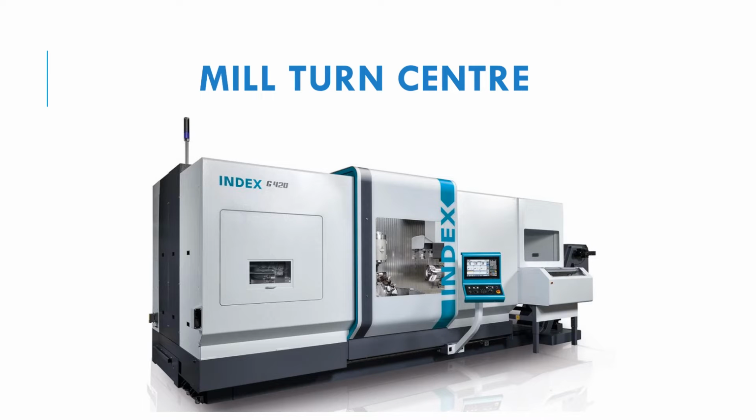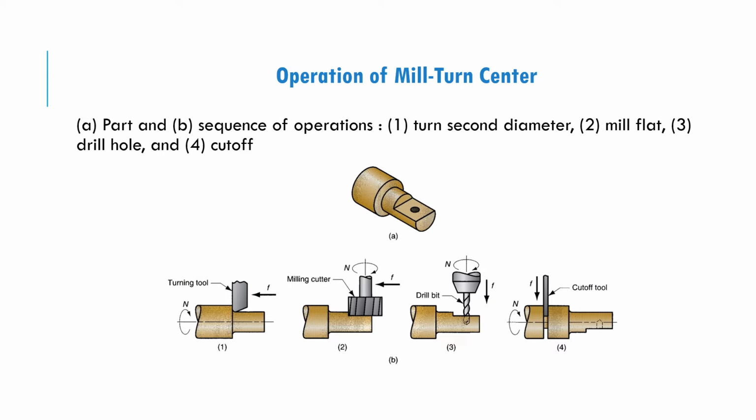This is an example of the latest mill-turn center available in the industry. This is an example of the operation of a mill-turn center. For example, part A is produced via the mill-turn center. What is the sequence of operations during this process? For the first one, the turning process takes place, where facing and shaping get the right dimension, and the diameter of the work part is produced via the turning process.